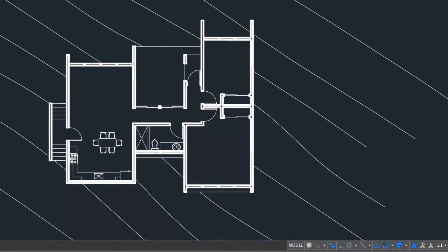A lot of times when I do an export, I'll actually do a save as, just so I have a second copy of the file. Doesn't really matter. You don't need to do it. The good news is SketchUp 2015 recognizes the AutoCAD 2013 file format, which is still the current file format. So AutoCAD doesn't update the files too dramatically every year. So anything from 2013 on is still the 2013 file format. So we're in 2015 here. If you have 2016 at home, it's all cross-compatible. So we can leave it as that.